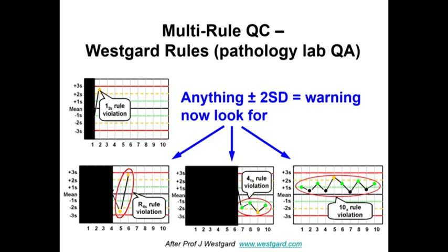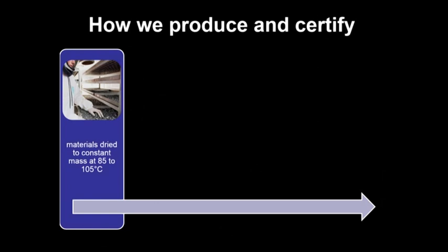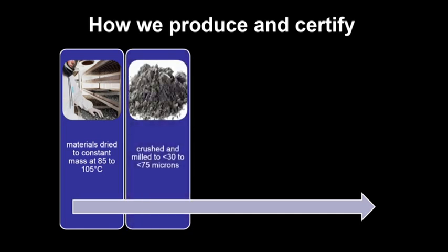So how do we produce certified reference materials? Well, we dry them at a lower temperature for sulfide-bearing materials to minimise any oxidation, especially for concentrates. We mill 100% minus 30 microns any precious metal content, or if it's an ore where the traces are very important for them to be homogeneous, then we'll mill it all to 100% minus 30 microns. Otherwise, the waste rocks, being the greenstone, if we're going to blend that with some gold ore, that can be milled to a slightly coarser fraction of 98% passing 75 microns.